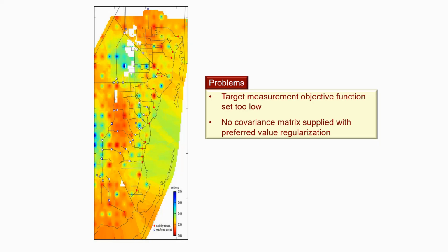Okay, let's look at a couple of examples. First, a not so good example. Now, this is a fairly disgusting parameter field for a calibrated model. You can see exactly where the pilot points are, marked by these little blotches, these little bullseyes spread throughout the model domain.